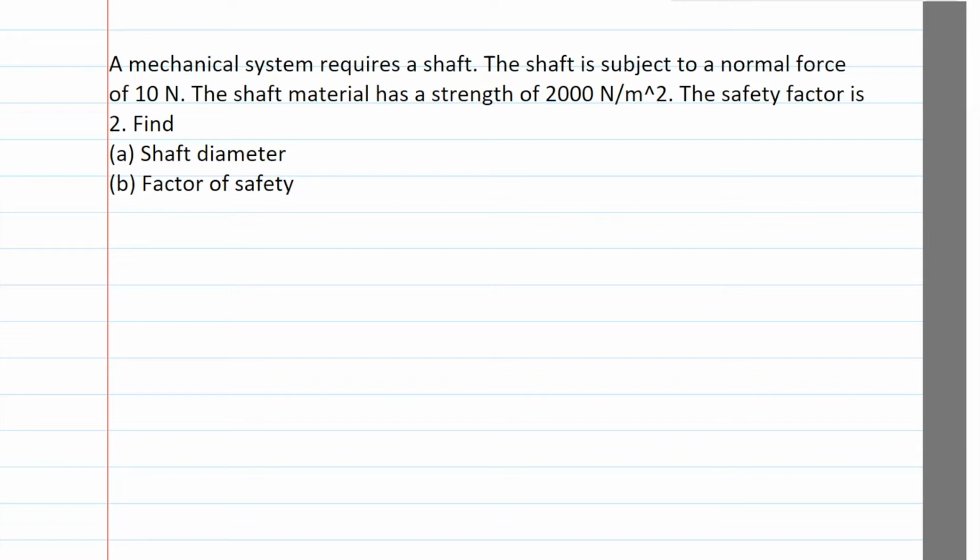Typically, for structures which you want to be lightweight, like aerospace structures, you want a low factor of safety, like 2 or 3. For structures where weight is not important, usually immobile things like bridges, you'll have a higher factor of safety. The bigger the factor of safety, the heavier your design. You can't have a very heavy car, or a plane, because it just won't move. But a bridge is not moving anyway, so it's fine.